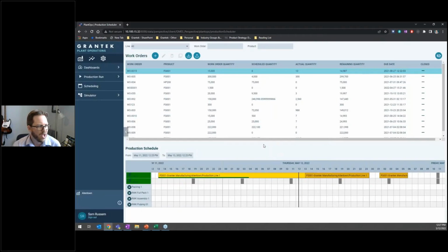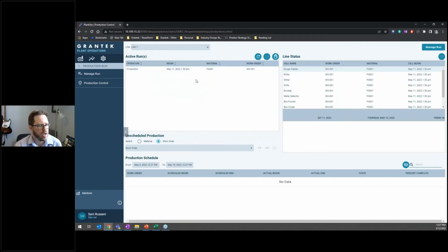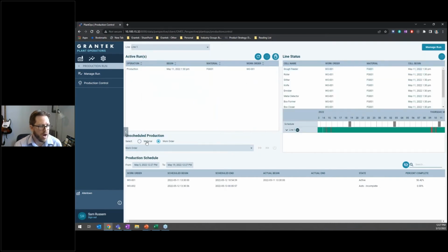We can also, again, if you're not maybe planning ahead of time, or if you do have emergency work orders that you need to fill, you don't need to have everything scheduled either. You can go into your production run and production control, select your line, and I can just say, I need to be running a FG001 right now, and I can just start that changeover right here from this screen. We can also schedule work orders that way too if we need to. Again, I'm not going to do that to mess up the data, but it's all an option that you have here. It also does support rolling changeovers or entire line changeovers.